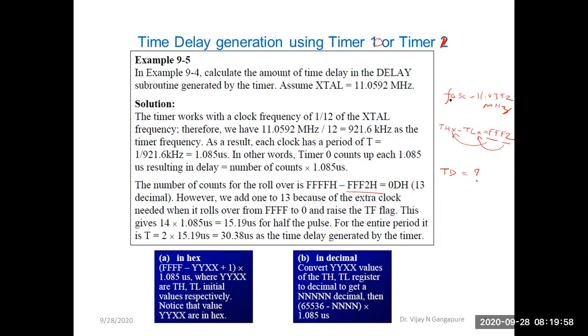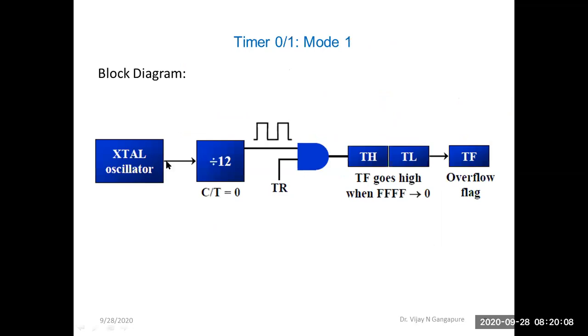For that I will refer to the block diagram of timer 0 or timer 1 in mode 1. Here the crystal frequency is given, FOSC equal to 11.0592 megahertz.